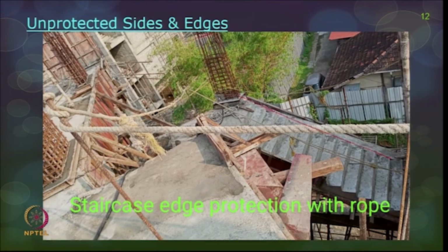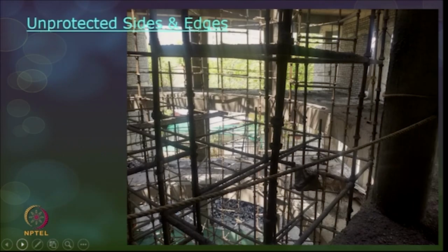You can see the staircase here, and there is no edge protection at all. Even this floor is not protected properly. This is an unprotected side and edge. If you see here, this complete opening is not at all safeguarded.